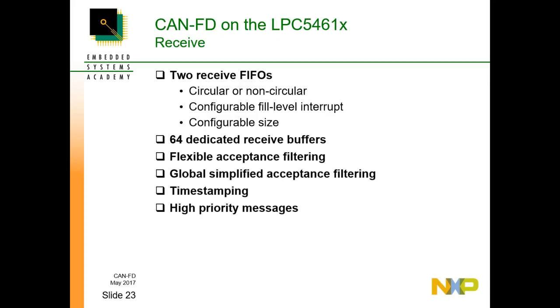Received message filters can optionally be configured to designate a message as high priority. When received, a separate interrupt occurs, and a status register allows the software later to determine which FIFO or message buffer holds the high priority message.